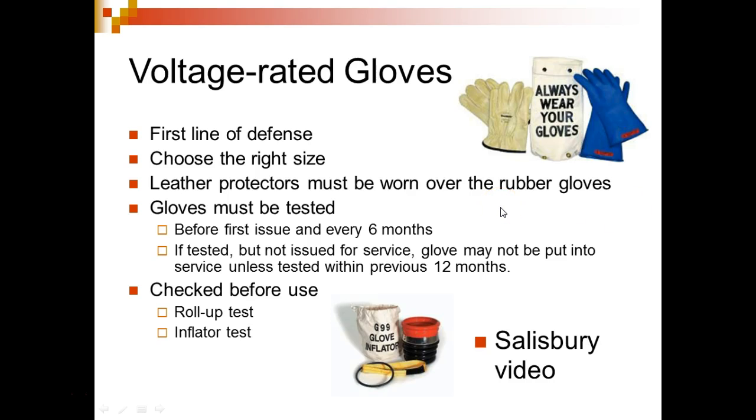Voltage rated gloves. First line of defense, choose the right size. Leather protectors must be worn over the rubber gloves in some situations. So sometimes some of them require rubber gloves. So what's the problem with rubber gloves? Yeah, you do sweat in them, but the problem is rubber's usually pretty easy to tear, right?